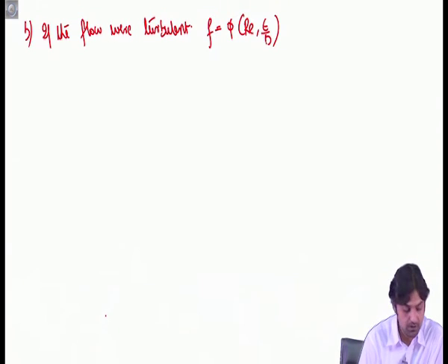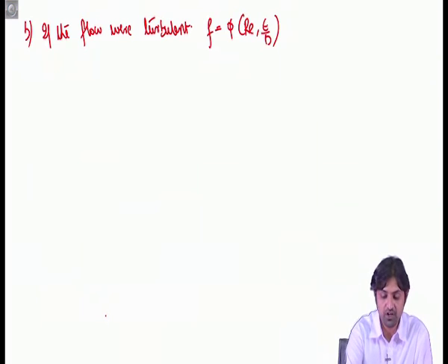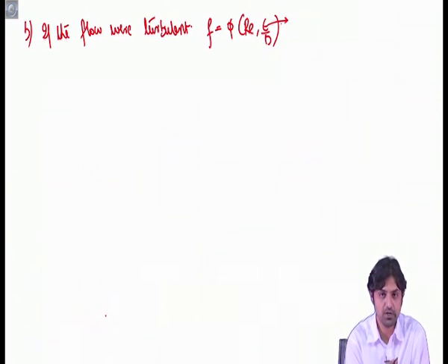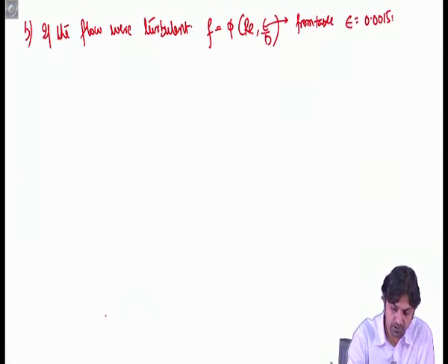I told you, if we know what type of pipe it is, we can look up the epsilon value. Of course, I have not written it here in the question, but if you look at the table, epsilon will come to be 0.0015 millimeter, because it is a drawn tubing.